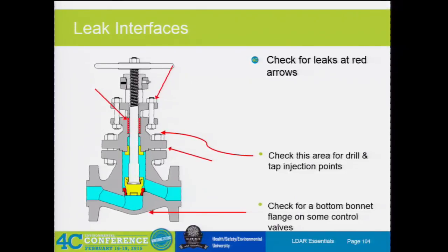And is it fairly common, if I get my terminology correct here, that the bonnet versus the bottom part of the valve, it could just come up the sides where the bonnet is bolted on? Is that correct? Is that fairly common? To leak on the bonnet? Where the bonnet is bolted on to the main part of the valve.